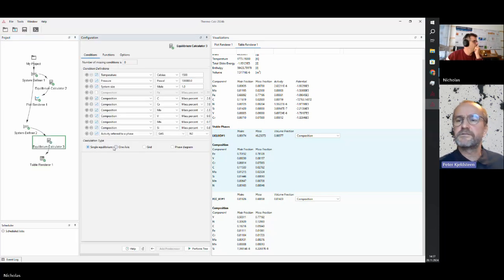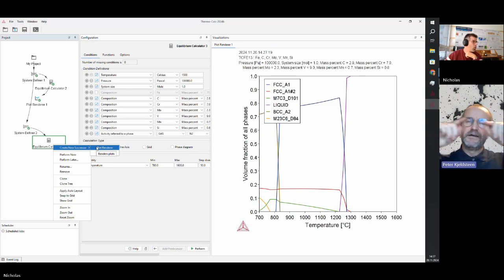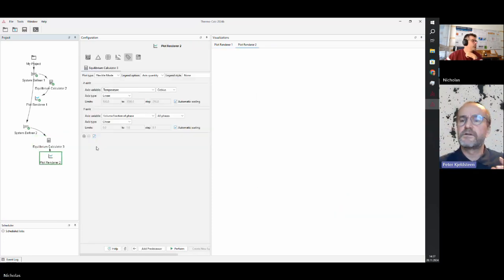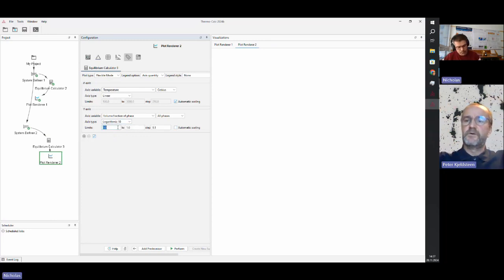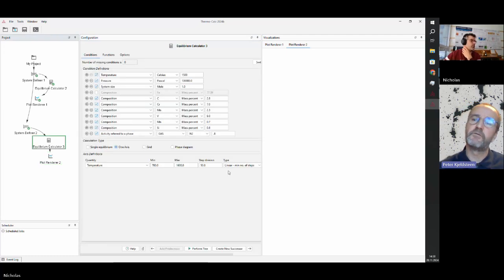One, it was an induction furnace, so it was induction stirring. So the steel was circulated like that. Okay. And furthermore, when we cast it, we didn't pour, but we had the teapot method. So we put a lid on and we pressurized it with nitrogen. So the deeper we went, the higher pressure. It was maybe a partial pressure of 1.2 bar instead of 0.8. Oh, okay. So we did a lot of bad things to the steel.